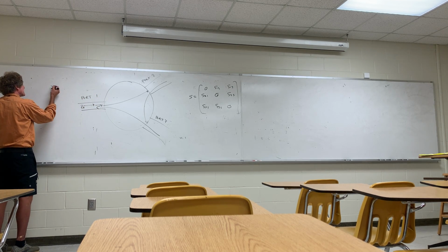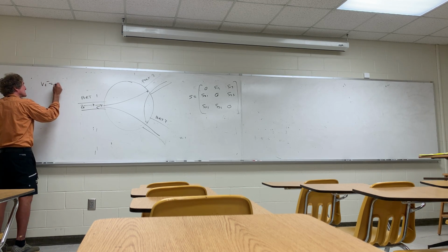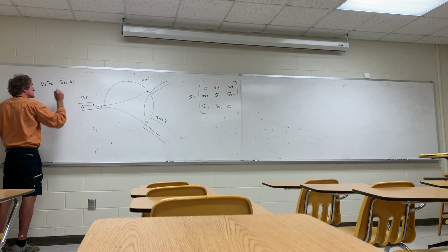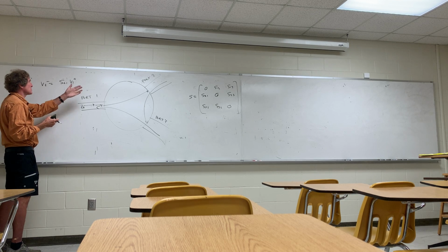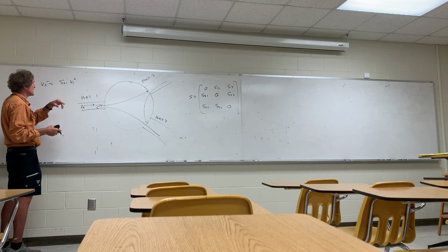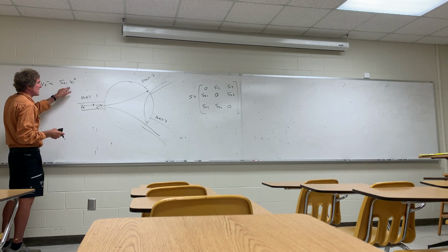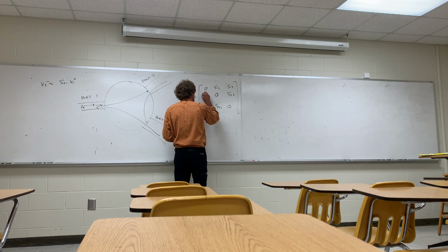Now the next thing I said is everything into port 1 comes out port 2. And if you think about this, if I have V2 minus, it's equal to what? S21 times V1 plus, isn't it? Y'all follow me? I mean, there are other terms, but if this is the only one of significance, then I said everything in port 1 comes out port 2 means S21 is 1. So I'm just gonna erase that and make it 1.